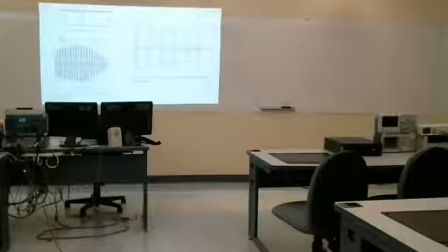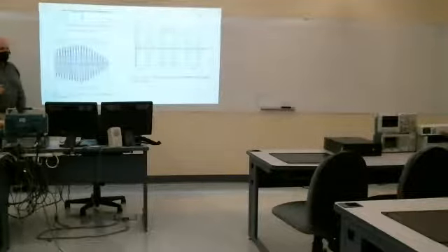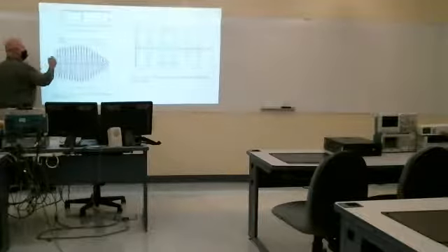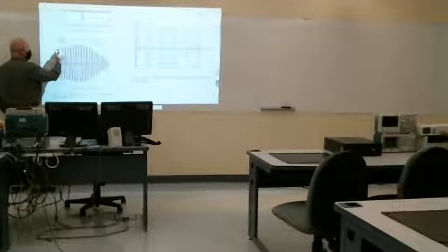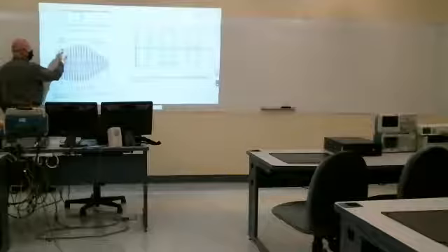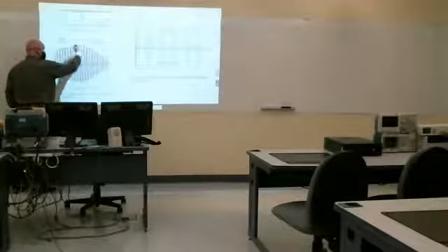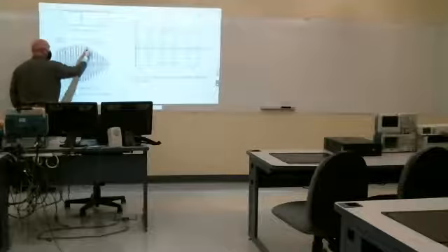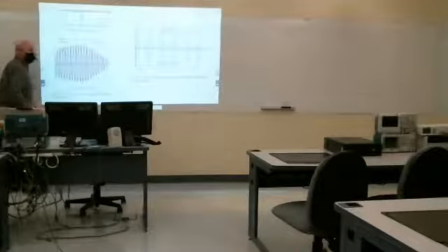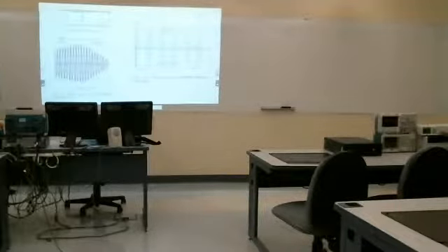Coming out of the wall, the amplitude is fairly constant, so you get a DC level from a half-wave rectifier. This is the same circuit as your half-wave rectifier. But now our capacitor here charges up, discharges, charges up, discharges. It will follow as our peaks change. Our capacitor voltage will follow those peak voltages, and that's exactly what we want to do.